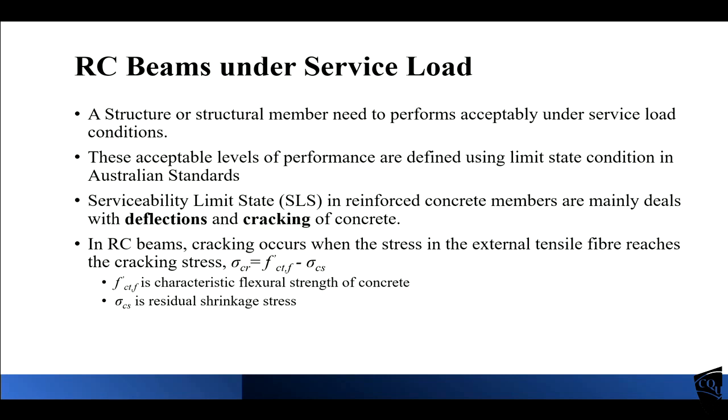Most of the chemical-related shrinkage will happen within the first 7 days, and will generally be almost zero after 30 days. The other one, shrinkage due to loss of moisture, is called drying shrinkage. It normally starts from 7 days and will go on over time.